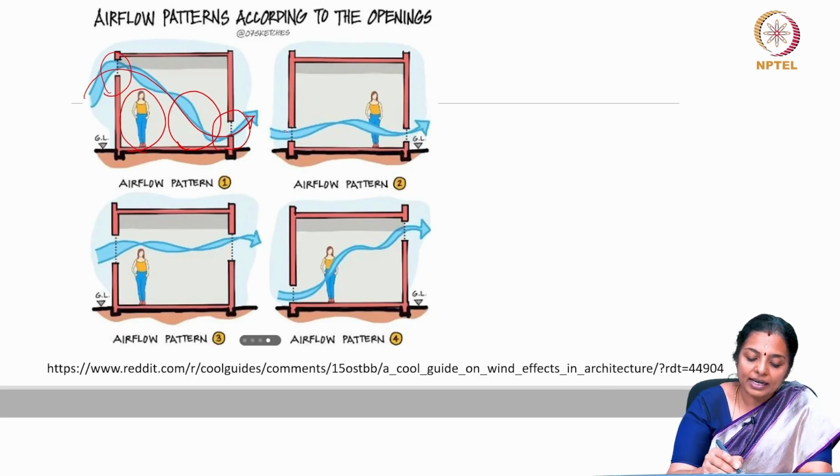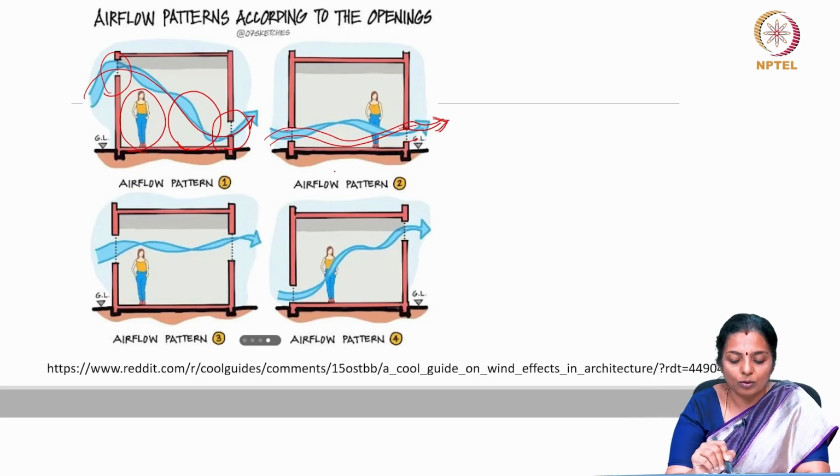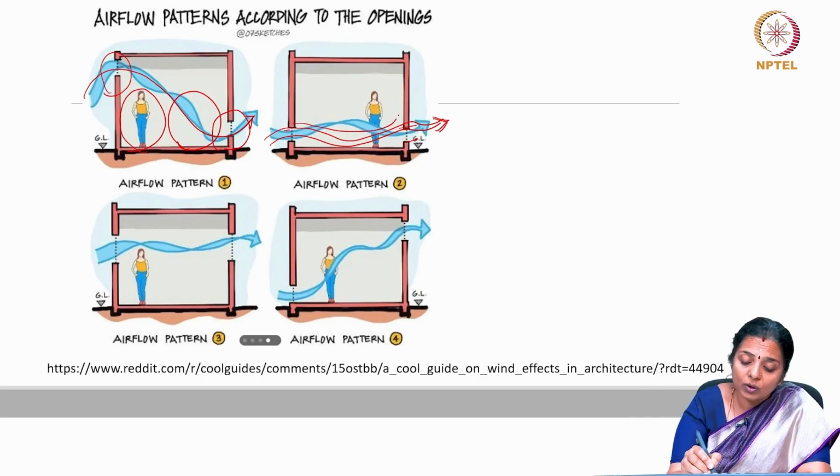When we have inlets at lower level, there will be a good indoor environmental quality because the stale air is always taken out. However, at working level, there would be completely stagnation and no air movement.